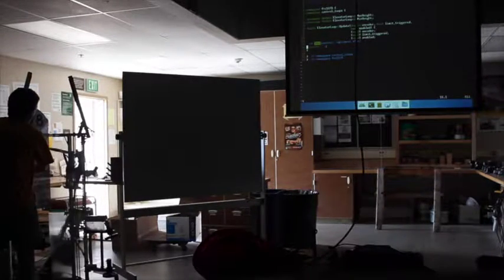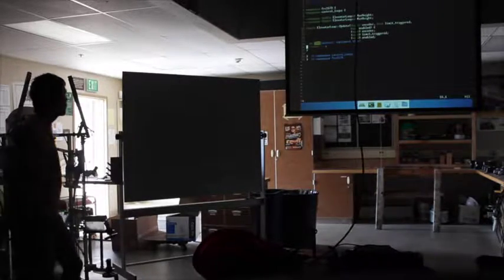Okay. So we start out, the elevator's right here, we turned it on. What's the encoder going to read? Yeah, zero. But is this 0? No. Okay, so what we need to do is figure out what is the position that we started at? Or the other way I like to say it is, what is the offset between what the encoder reads and our absolute coordinates?